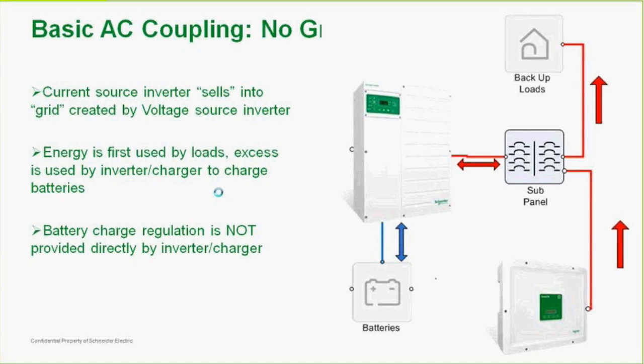So what we see here is a grid tie inverter coming into the sub panel. If we go back to that earlier slide that I said was important about different functionalities of inverters, this battery-less inverter needs a grid source to synchronize to. So in this case here, think of this sub panel as a grid. We have the battery-based inverter providing a sync signal for the grid tie inverter. And we can run loads, and we can utilize this energy.